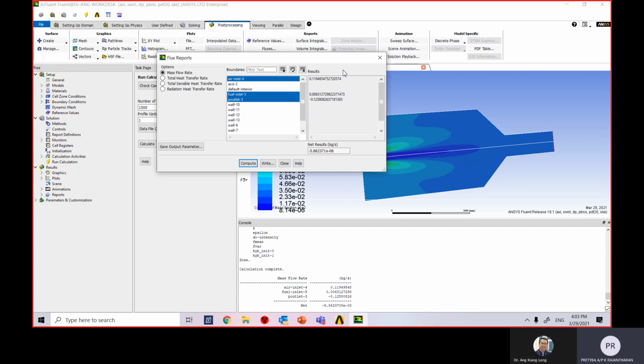There it's 10 to the power -7, but here I got 10 to the power -2. You get what? 94.04 times 10 to the power -7 for the net result, is it? Yeah. Okay, so that one you need to check again. This is maybe because of the boundary condition that you set up just now. Maybe some number you didn't key in with the proper decimal place.